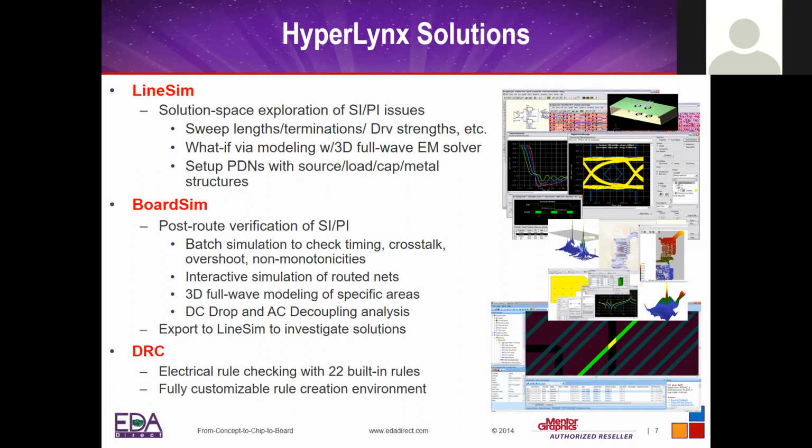You might think that reset is a static signal. It's not. It might be next to a strobe line or data line, and this switching activity could be coupling into those reset lines. So that's just one example of DRC.